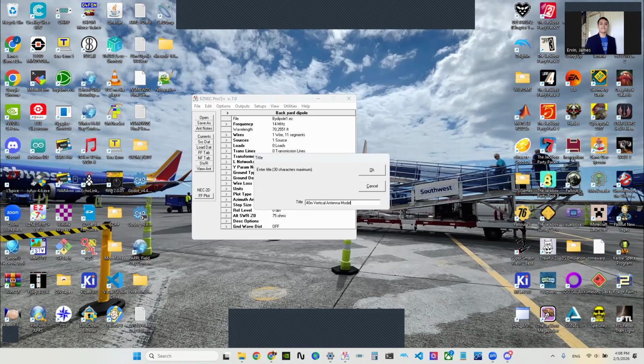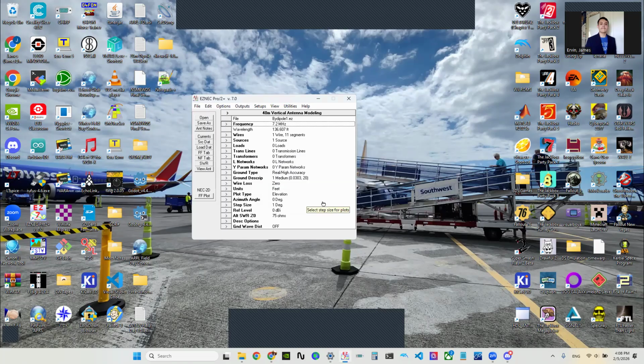Y'all can name it whatever you like. It's up to y'all. Have all y'all named your antenna so far? Sweet. Okay. Next thing we're going to set the frequency to our frequency of operation. Say we want to operate 40 meter voice, we're just going to enter 7.2 megahertz. So y'all can go put that in.